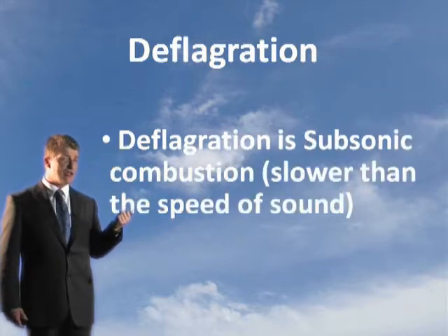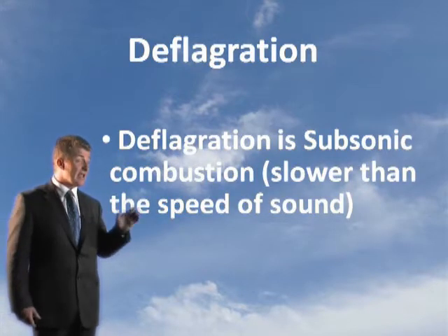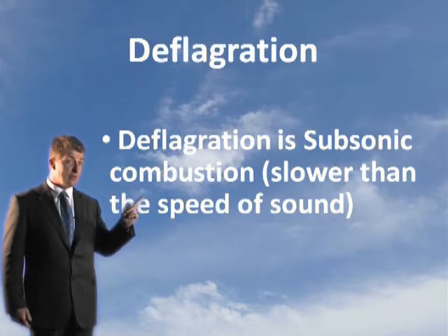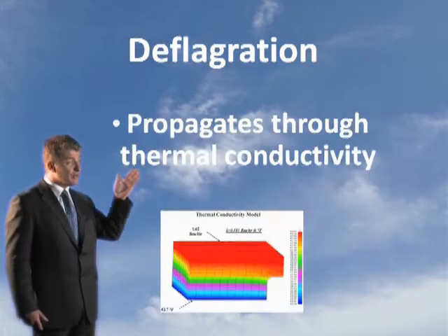Now, deflagration is subsonic combustion. In other words, it is slower than the speed of sound. And the principal heat transfer mechanism, in other words, how it propagates, is through thermal conductivity. What happens is the hot burning layer heats the next layer and ignites it. So it's through thermal conductivity of the individual layers. So it keeps travelling through the material and it then ignites it.